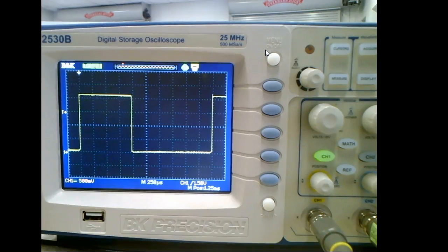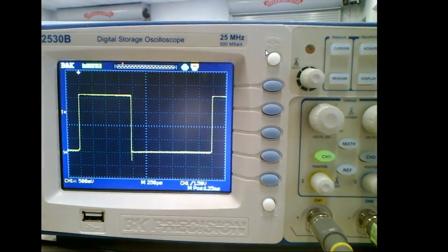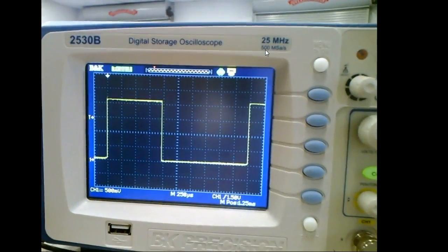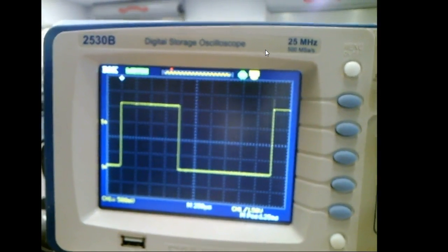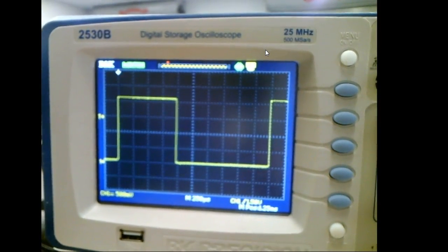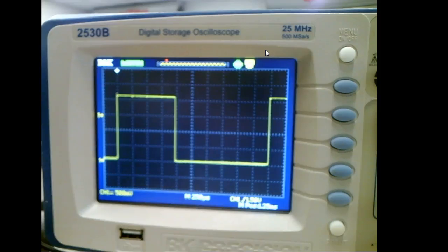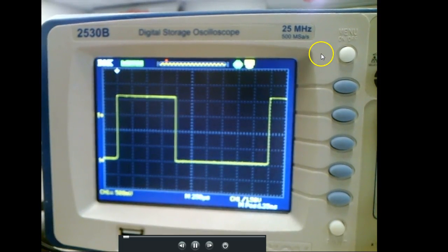Yeah, I got 500 millivolts per division. I got 4 divisions, which gives us... Is that 4 divisions or 4? Okay, so it's 2 volts. I'm sorry. So it is 2? Yeah. So who said Rich never makes mistakes? Anthony said that? But you may make one, but you fix yourself right quick, Mr. Rich. Well, what's nice is I know when it's wrong, right?